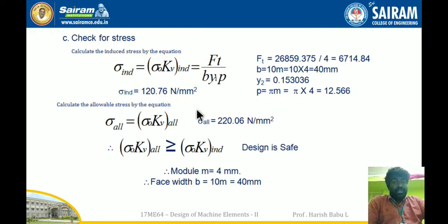Since from these two equations sigma allowable is greater than sigma induced, the design will be safe. So I can say that module 4 will be suitable for this particular problem, and the face width will be 40 mm. The next problem we'll see in the next video.